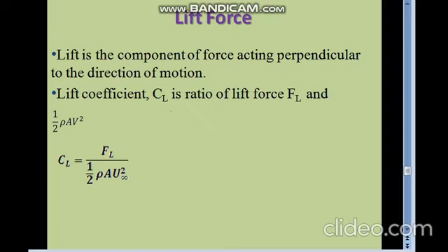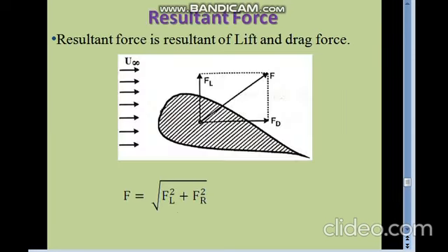Lift force is similar to the drag force. It is expressed in terms of the lift coefficient CL. So CL is lift force FL divided by half rho A U infinity square, where A is the projected area in the direction of the flow.